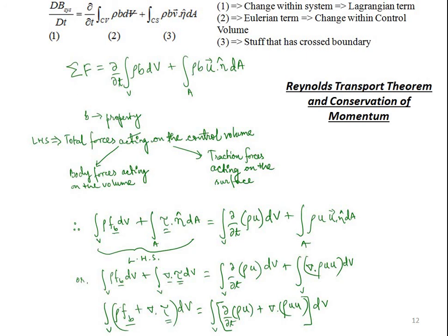If we take an example in a solid object, if we apply a stress here, the shear stress experienced is tau x in the x direction, and some amount of shear stress due to x will be in the y direction, and some amount also in the z direction if it's a solid cube. If it's simply an area, then some amount of shear stress will be in the x direction, and some component of the x shear which we have applied will be in the y direction. That will be denoted by tau xy.